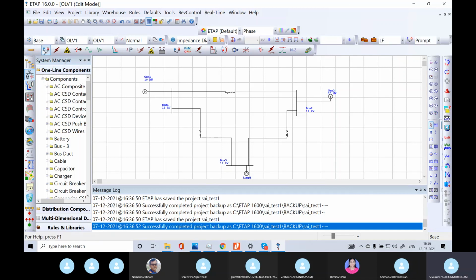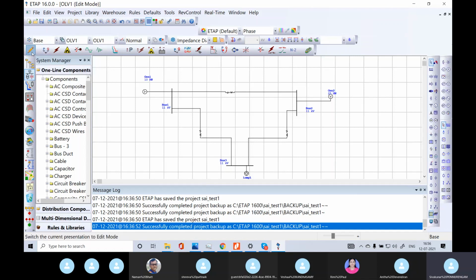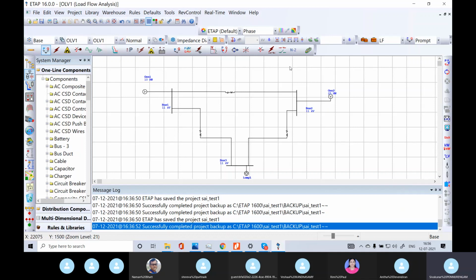So first here we are going to consider the load flow. Please see, this is edit mode. These are all the simulation modes, right? Whenever you press this pencil symbol, the window will work in the edit mode. Now I am going to the power flow mode. In the power flow mode, we run the load flow analysis. Load flow analysis can be run on this diagram. Next one is auto run flow on and off, disabled or enabled based on switching, if it is available. But in this circuit we have not fixed any switching modules.